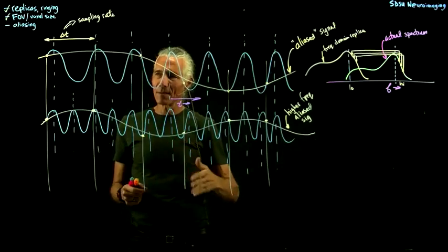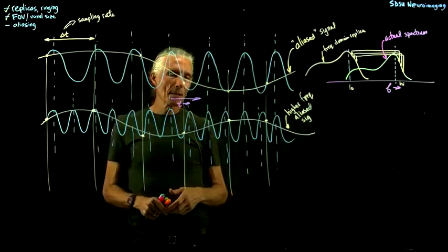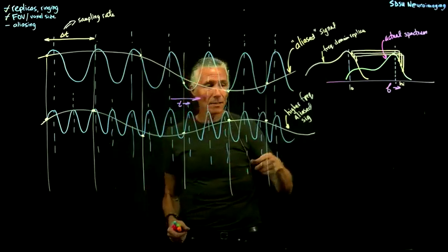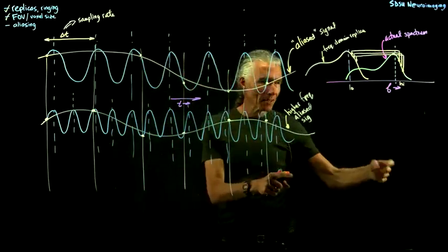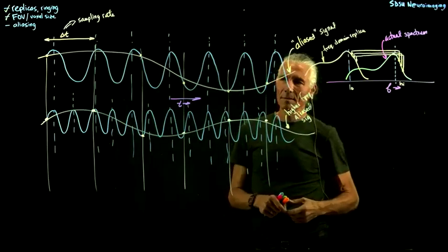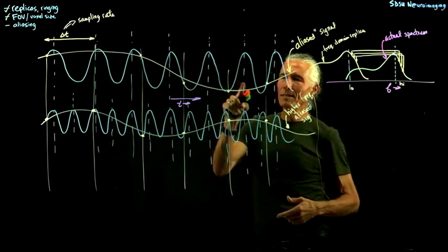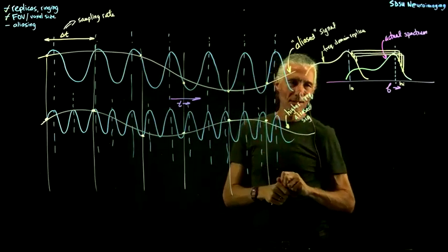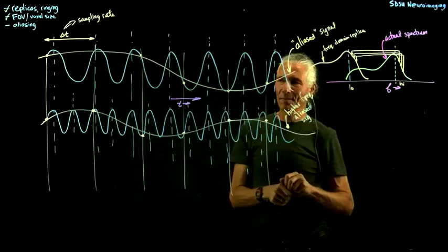It's hard to collect it fast enough. If you could collect an image every half a second, then that would be fast enough so you could actually see that signal in your time course and filter it out. But once you've got this aliasing, it's hard to deal with after the fact.